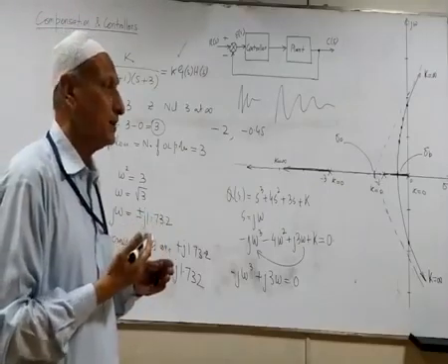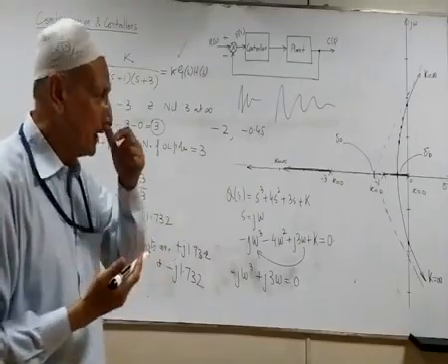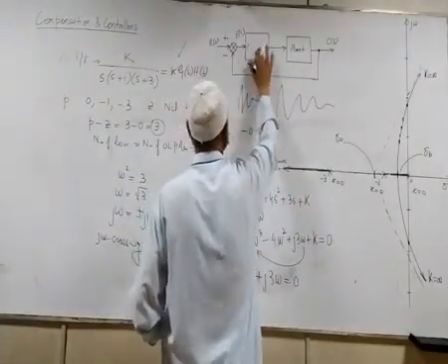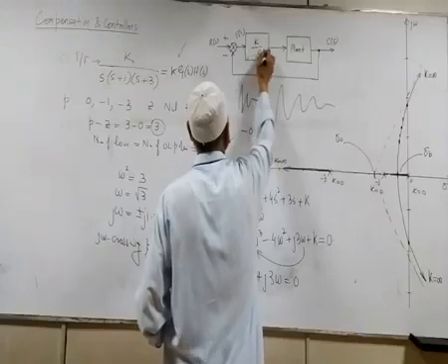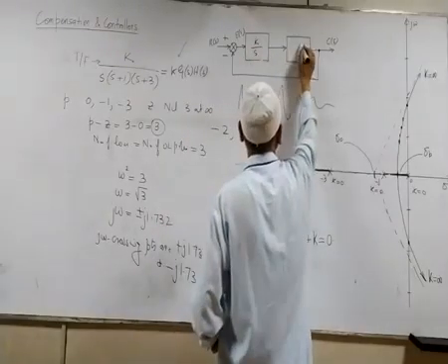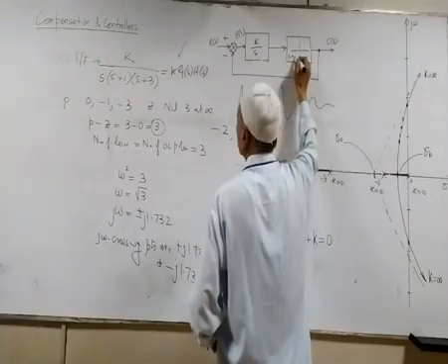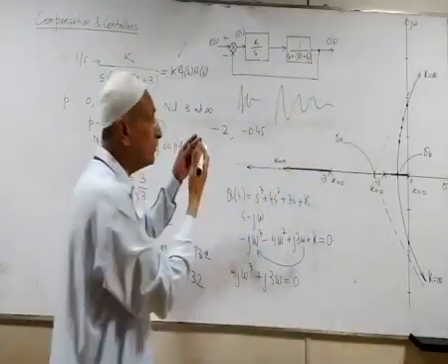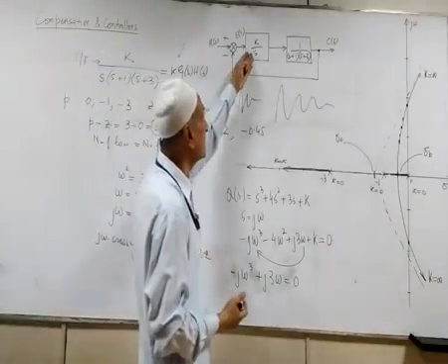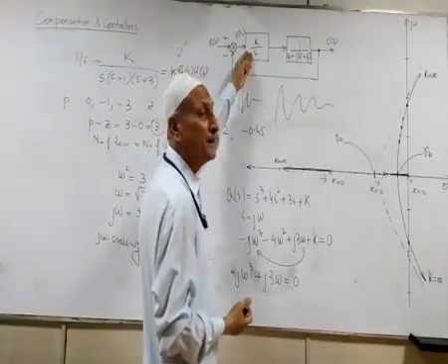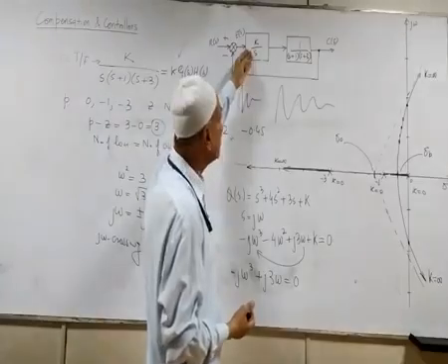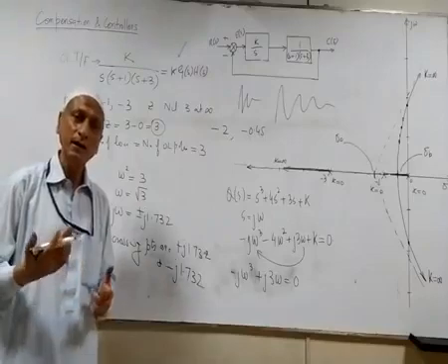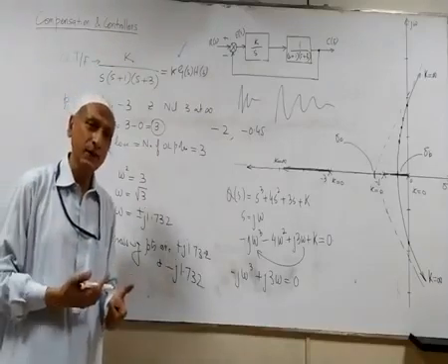Such that the system should have adequate gain margin incorporated. So anyhow, the conclusion is that if we consider this one as a controller, that is K over s, and the original plant is then 1 over (s plus 1)(s plus 3), with the original plant all we have done is to incorporate an integral controller. This is an integral controller because 1 over s is integral basically, and s is the derivative.